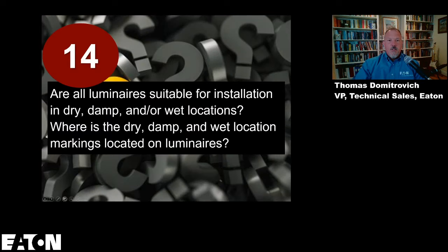So with regard to 14, are all luminaires suitable for installation in dry, damp, and wet locations? I would say no. You have to have it listed for that application, and it says where the dry, damp, and wet location markings are located. We saw that as part of the instructions, right on the units themselves.